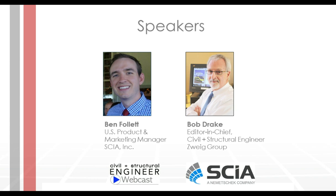Okay. What kinds of dynamic analysis can you perform in SCIA? For dynamic analysis, you can do anything from a free vibration analysis, which obviously is a very standard type of dynamic analysis. You can do forced vibrations in the sense that you could do a harmonic or a harmonic band analysis. We do seismic analysis in a dynamic feature where we're either doing an equivalent lateral force procedure or a full-blown modal response spectrum analysis.